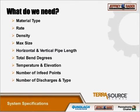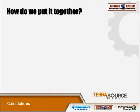And then we also just need to know the number of discharges and the type. You've got a diverter valve that splits the run into two. Typically, the longest pipe run is going to be what's critical, because it's, as we say, the worst case scenario, but we would like to look at all the piping runs to make sure that the shorter run doesn't have, say, a larger vertical section or more elbows, which would actually turn out to be the worst case scenario. And then the type of discharge is, of course, important, because there's going to be different pressure losses associated with each different type.